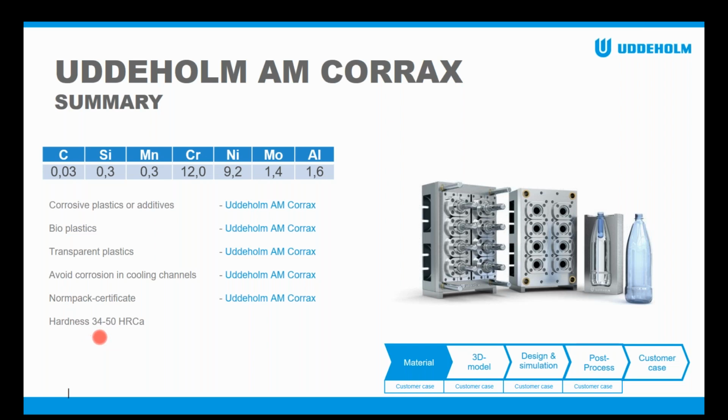After printing it, it has a hardness of 34 Rockwell, and you can age it to a hardness of 50 Rockwell. You can actually deep cool it to maximize the material at 52 Rockwell, but 50 is usually what we aim for.